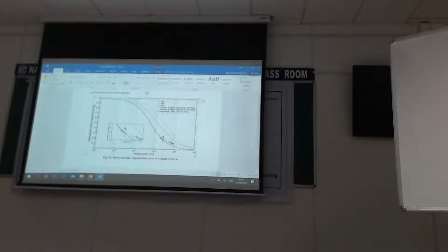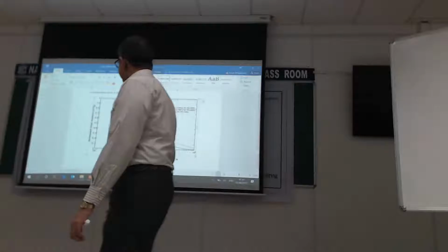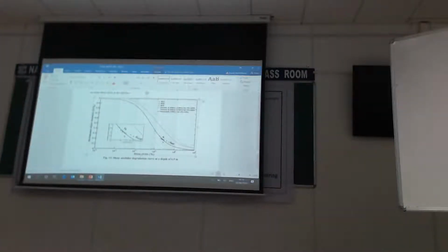What we discovered was we're closer to the Darendeli curves, which are more for normally consolidated clay. So now we are in a position to actually apply the corrections the other authors were asking us for, because we now know how our stiffness is degrading with the earthquake cycles.